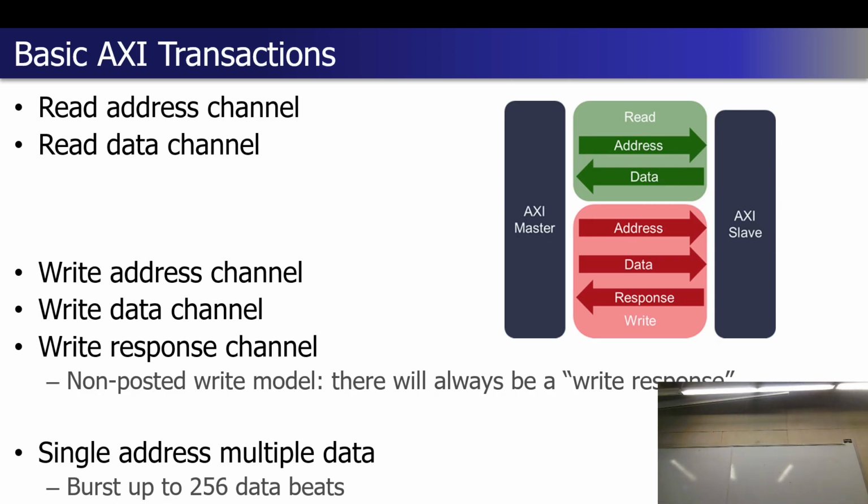So this is one view of the AXI full kind of interface. There are 5 different channels. That's the first thing you'll read about when you read about AXI 4. Channel's just a more complicated sounding word for just a set of signals, set of wires, set of interface ports associated with a part of a transaction. So there are 5 different channels, which is different than how other buses would potentially do it for different parts of both the read and the write operation we may want to have.